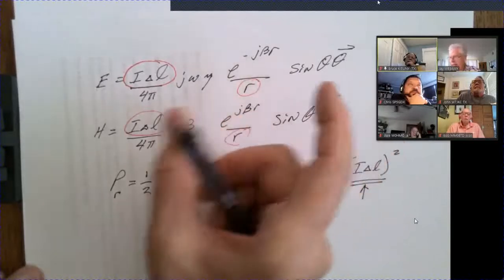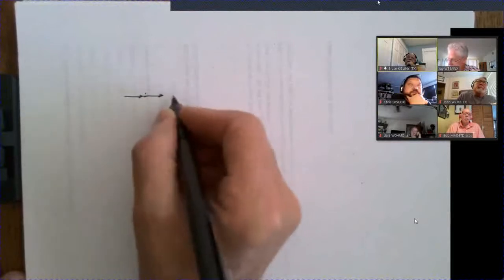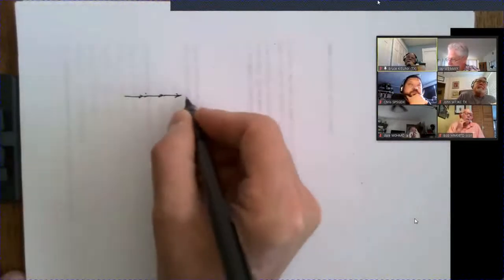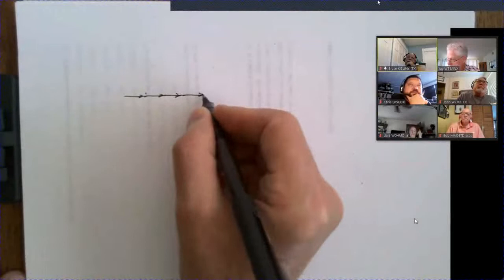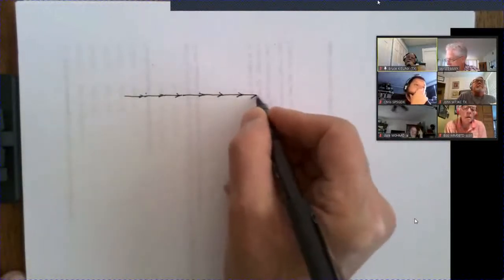So you can make that as that distance. And this is how modern programs and antenna analysis work, you can break up your antenna into a series of segments, okay? And each one of your segments has a certain length and a current assigned to it, okay?